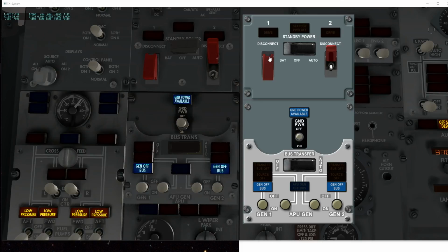Now in the original 737, the 200 and 300 up through the 400, those were even the classics of 5 and 6, those were anything before NG, they had a constant speed drive unit that was basically, think of it as a little hydraulic, almost like a constant speed transmission, if you will, a fluid driven thing that would maintain a certain frequency so that the generator would turn at a constant frequency and produce power.